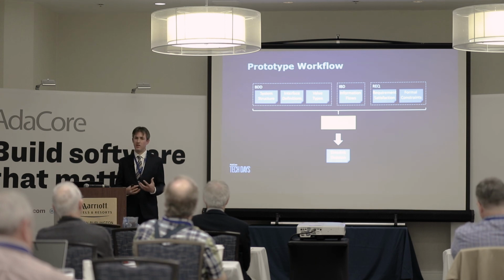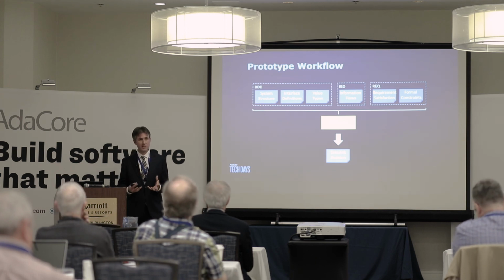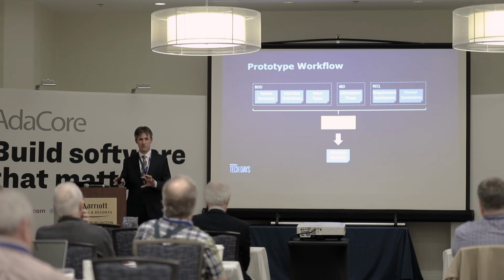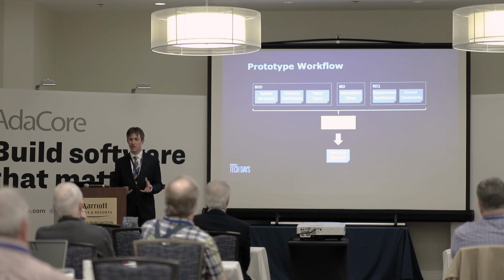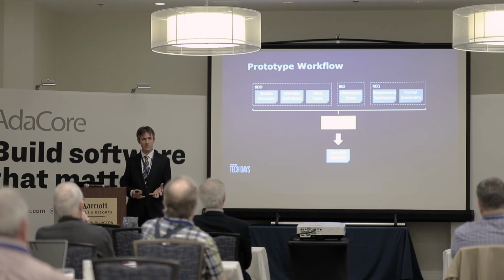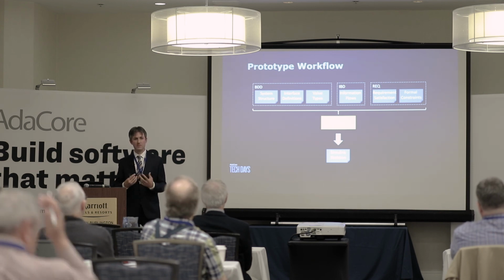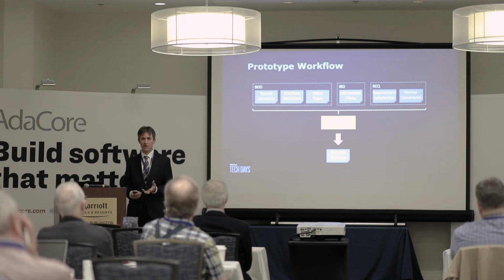We can take information out of the internal block diagram, which gives us the information flows that connect these components together, and use that to generate connections so that the subsystems in Simulink are connected together. Finally, and most importantly, we can take information out of the requirements diagram, where requirement satisfaction is linked to components, and where formal constraints have been introduced, and we can synthesize synchronous observers that can execute at the Simulink level.